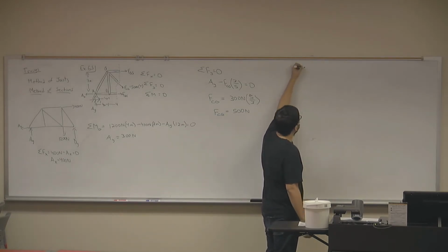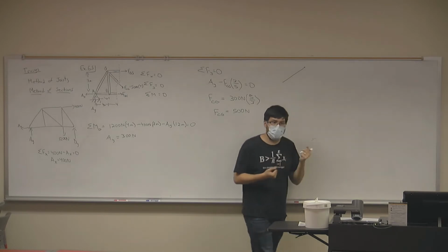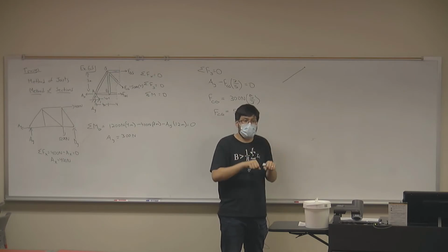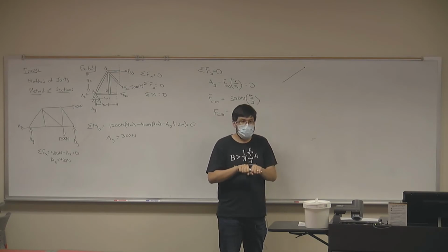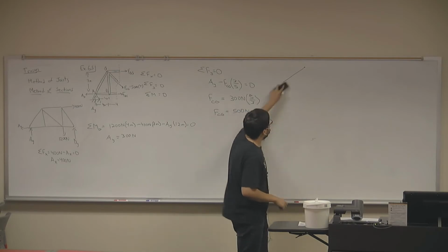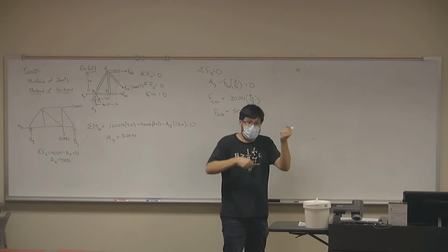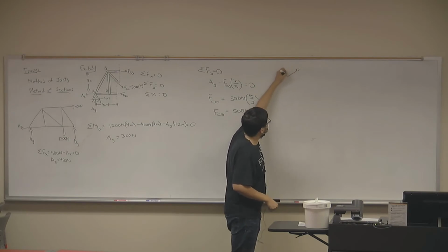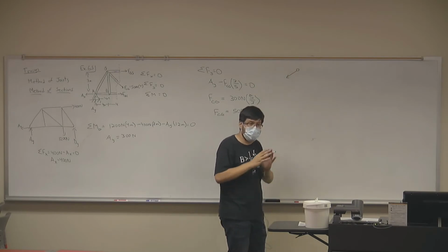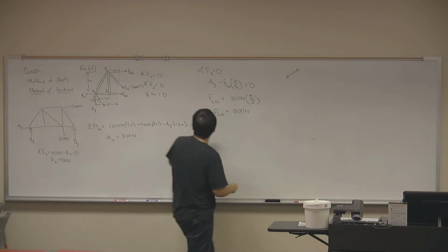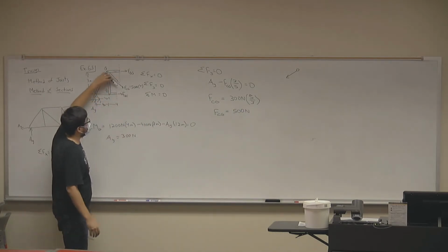because you have a truss, which is a rigid bar, this bar does not experience any bending. It doesn't experience any shear, at least not externally. So there's only 2 forces that this bar can really experience: tension and compression. If we're looking at it in the context of the joint, if the bar is in tension, then the joint feels pulling, right? So you take your force to be pointing outside of the bar, from the bar outside of your system. In this case, I drew my force as if it were pointing outside of my system, right?